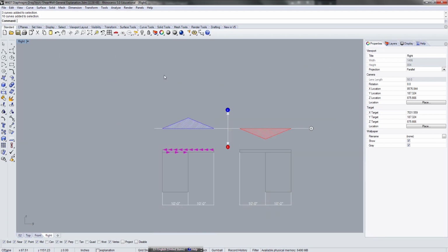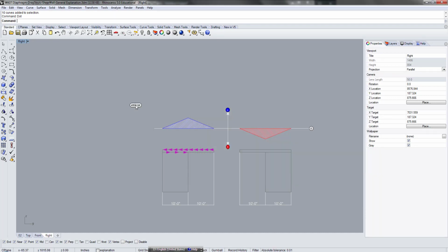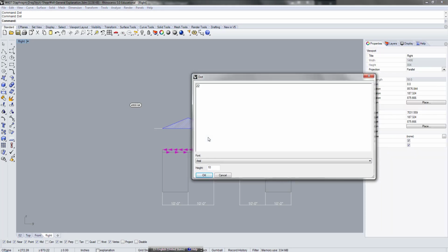But the idea was that, let's say there's 4,500 pound force shear total, right? But here it was 225 pound force per foot on the top side. The bottom side, it was 450 because the length was half.